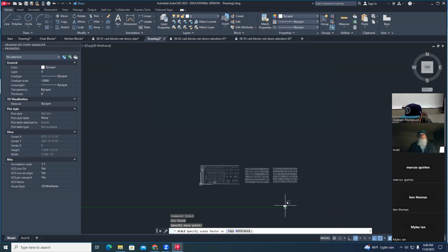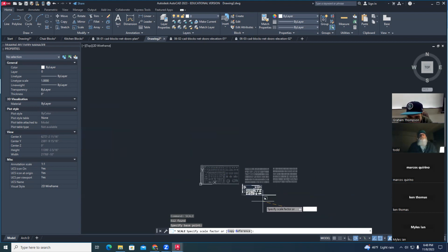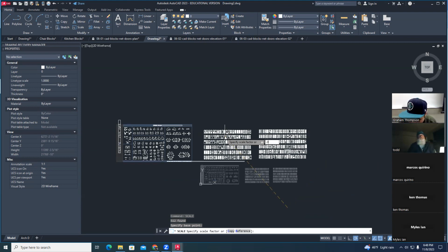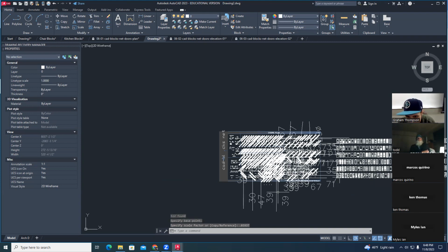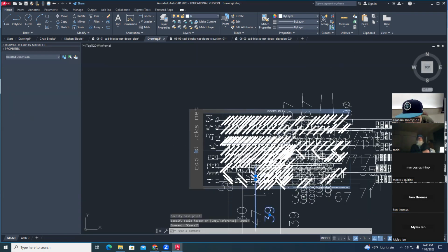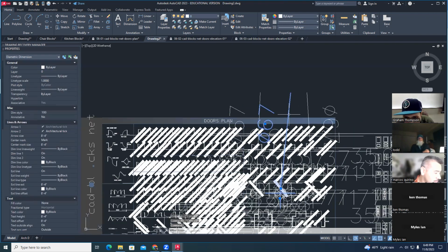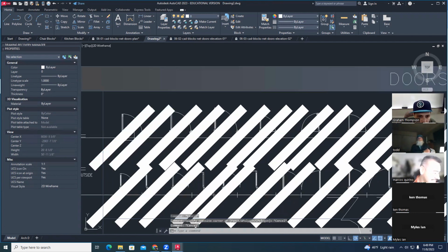And as I move it out, you can see it's really small. I can move it way out here. Okay, but what I want to scale it as, I don't care where I scale it. I care what I scale it as, right? So I don't care where I drag this. What I want to do is type in 0.03937 and hit enter. Once I do that, it'll make it really tiny. What the heck just happened? Whoa. All the dimensions on the doors went whack. That's okay. We don't want the dimensions anyways.